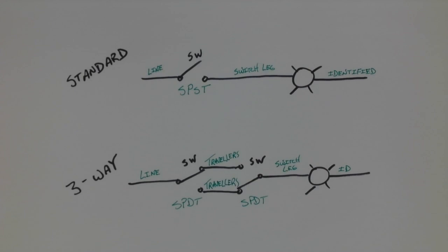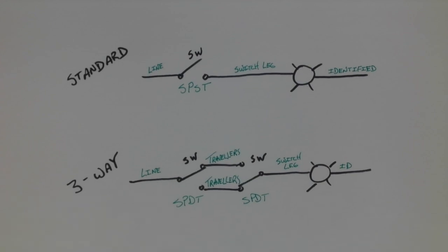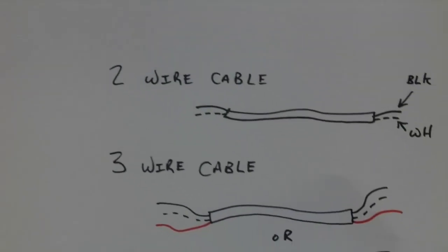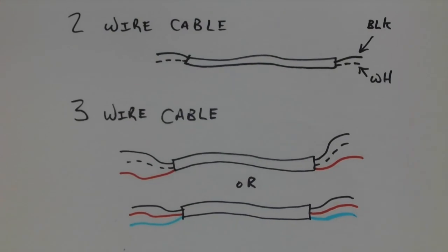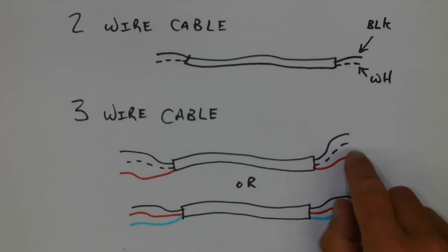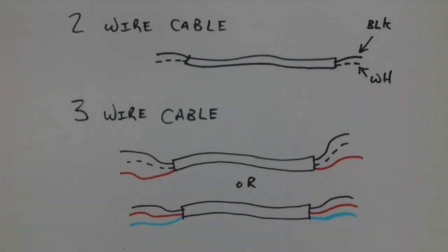So where do the challenges come in when we're dealing with cable and these two very standard types of lighting circuits? Well, first we need to understand that cable will only come in a few different color variations, unless you're getting into some really specific industrial controls. But usually at that point, we are not working with a 2 or 3 wire cable, but something in the realm of 10 or 12 conductors.